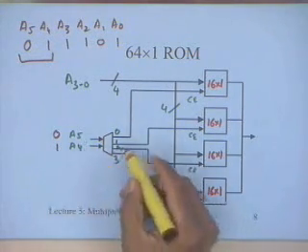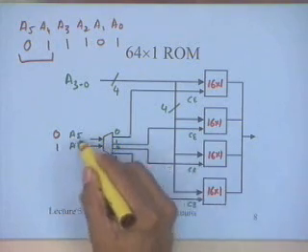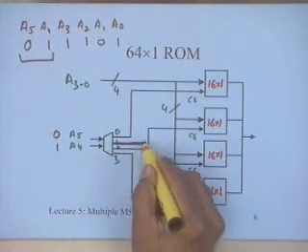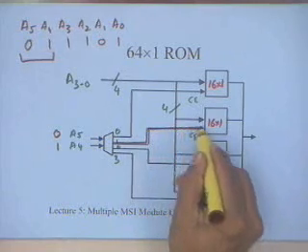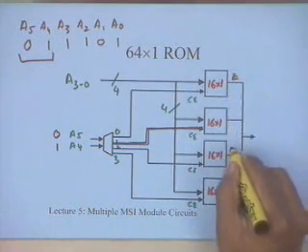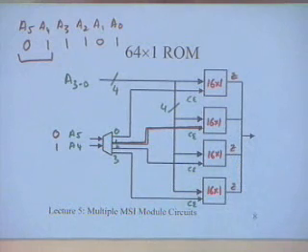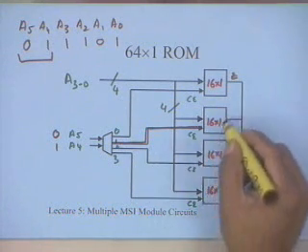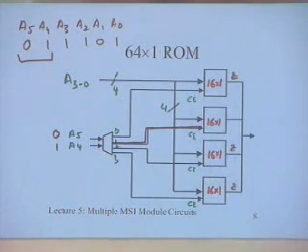So the effect of this is that this particular decoder output is going to be active and the rest of them are inactive. That means the rest of these outputs are going to be Z, high impedance. They are like switches not connected, because this is the only one which can have an output of 0 or 1.